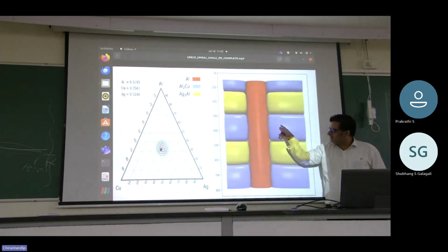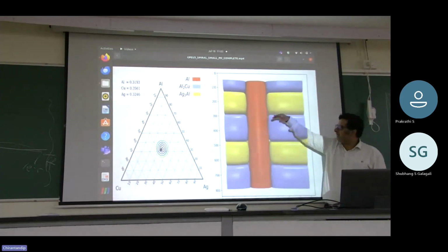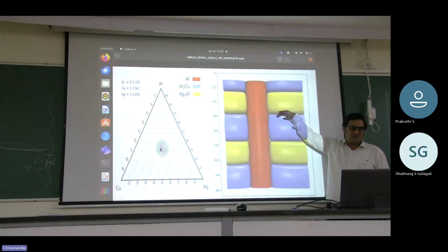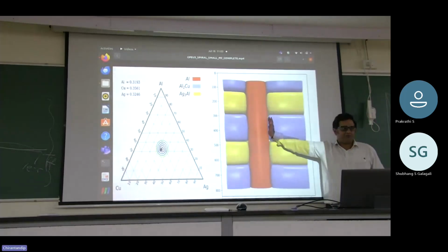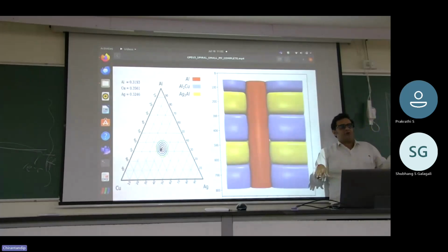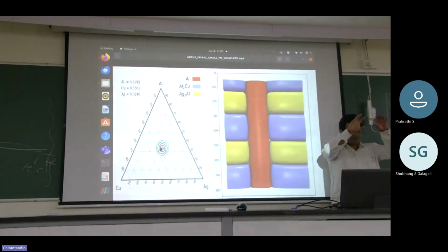Similarly, there could be an orientation relationship between this and this. Now, this sets the interface character of this and the interface character, and they can, in principle, have different types of anisotropy. So what we have introduced now: previously in the code, we could have only one anisotropic formulation. We now have interface-specific anisotropic formulations, which means we have a set of anisotropic functions defined separately, and we can associate with each interface which anisotropic function it has.